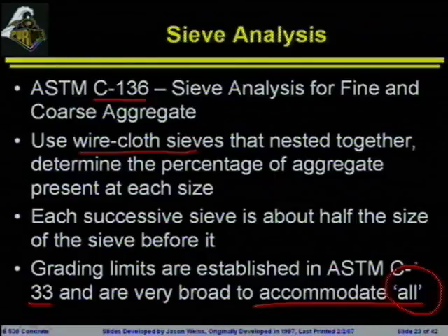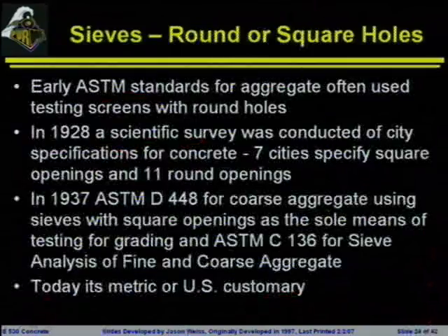This means that when specifications go through ASTM, they are fairly broad so that they satisfy everyone's requirements, whether you're in Washington State, Hawaii, or Louisiana, and everybody's going to have aggregates that have slightly different properties. One of the things that I will point out is just controlling your aggregate to the ASTM specs is going to be a problem for quality control down the road, and we will talk a little bit about this.